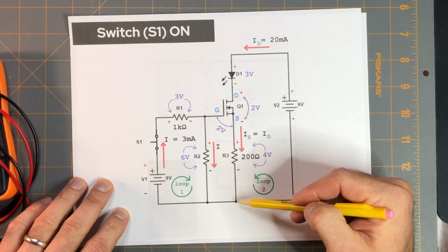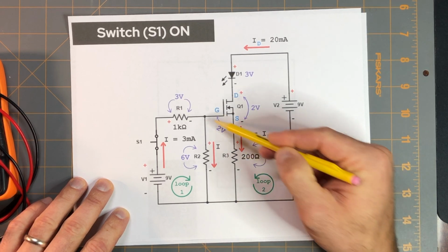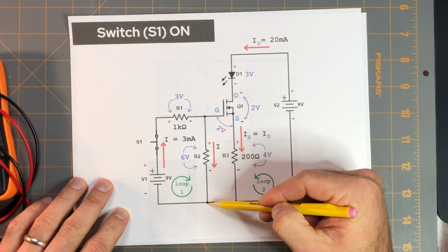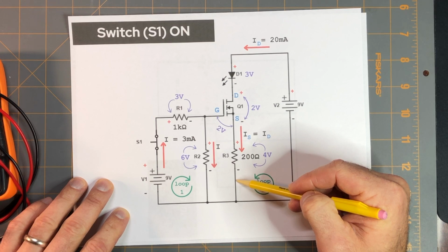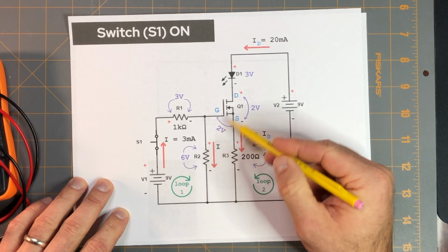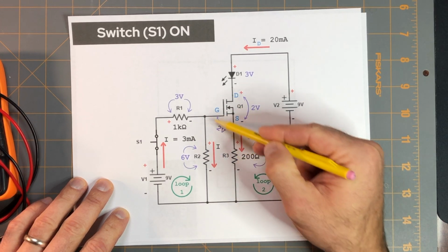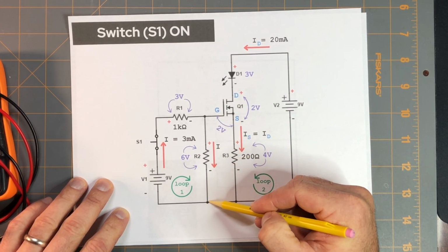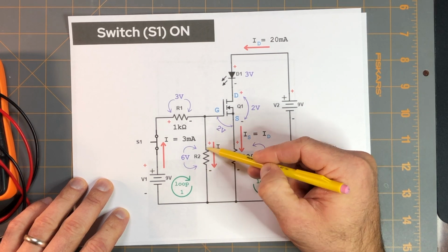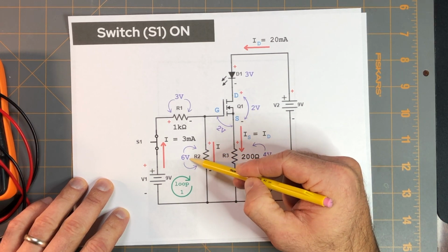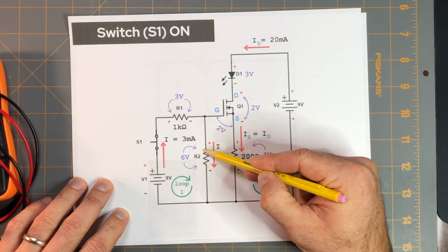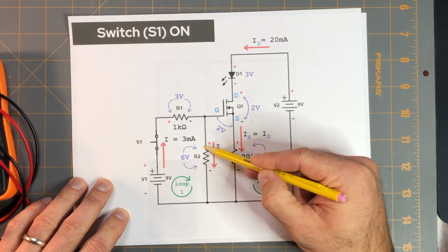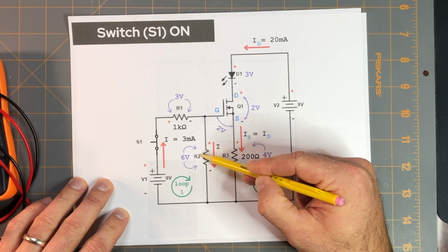That's the voltage potential between these 2 points, which should be the same voltage potential across these 2 points because they're in parallel, and voltage potentials in parallel with each other are equal to each other. So 6 volts across these 2 points, 6 volts across these 2 points. Now, knowing that the voltage drop across R2 is 6 volts, we can't quite figure out the value of R2 because we don't know it. That's what we're trying to figure out.